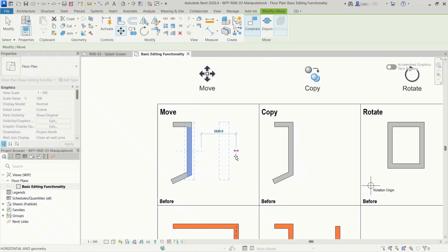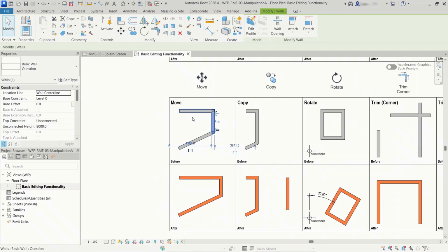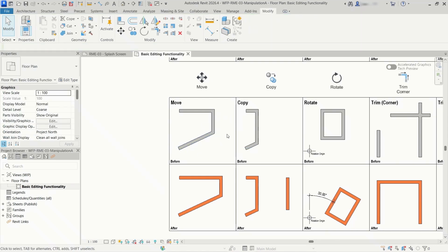Key notes: dragging without the Move tool is possible, but often inaccurate. The Move tool allows for vector-based movement, direction plus distance between 2 points. Numerical input for exact shifts. Works best when snapping to references or using dimensions.